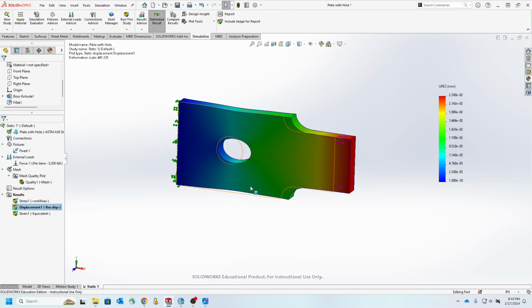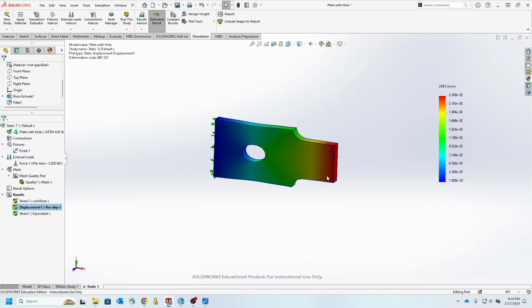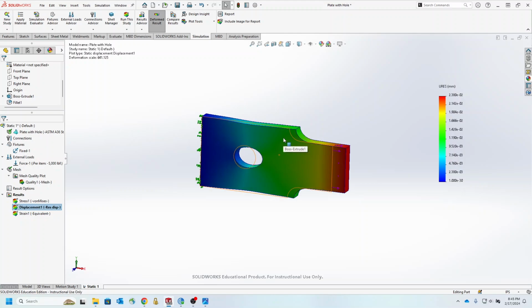This is because the displacement that you see on your monitor in SolidWorks is an exaggerated deformed result. They just want to show some exaggeration, because if they stuck to the true value, it would be too minimal to apprehend.